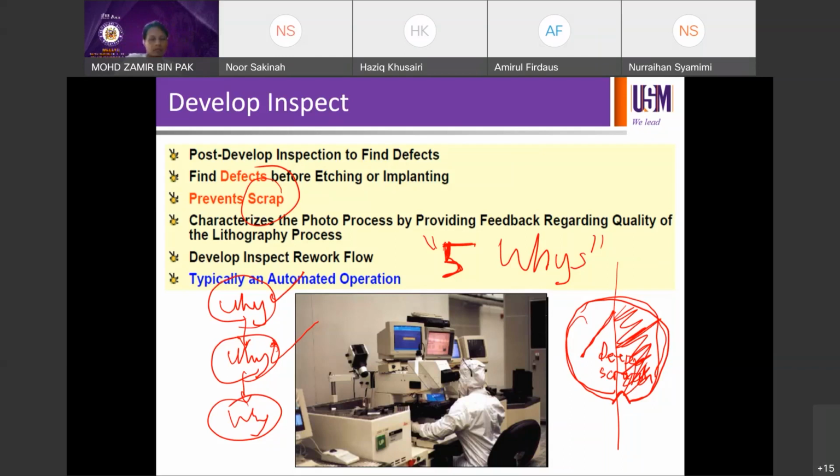Okay, let's say we find, if that's the question, why did the robot arm not place the wafers correctly? Maybe your finding is, I've done this a few times before, sometimes the X is off. Sometimes X is this way. We've seen the video in the e-learning. Say if this is your Y, the robot arm is like tweezers. If this is your Y, if this is your X, sometimes this is your theta. Theta is its angle. Sometimes the theta is off, or X is off. Sometimes Y is off. Sometimes many are off. X, Y, theta all off.